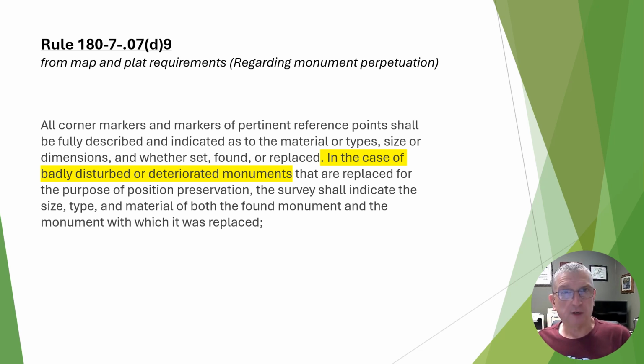I go get a rebar out of the truck, cap it, and drive it right there where I found that 1-inch pipe. My plat will say IPS 5/8 rebar at badly deteriorated 1-inch open top pipe found. Then everybody knows what's going on. As you remember from last semester, for a monument to be held as controlling, it must be called for, match the description, and appear undisturbed.